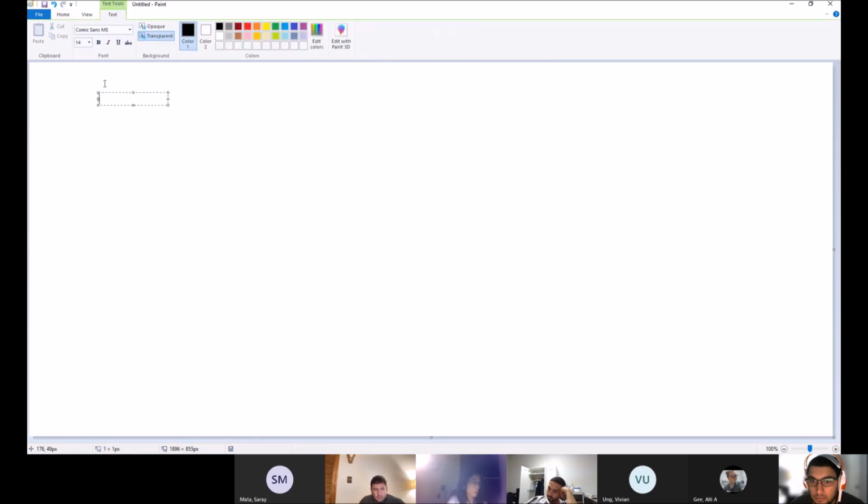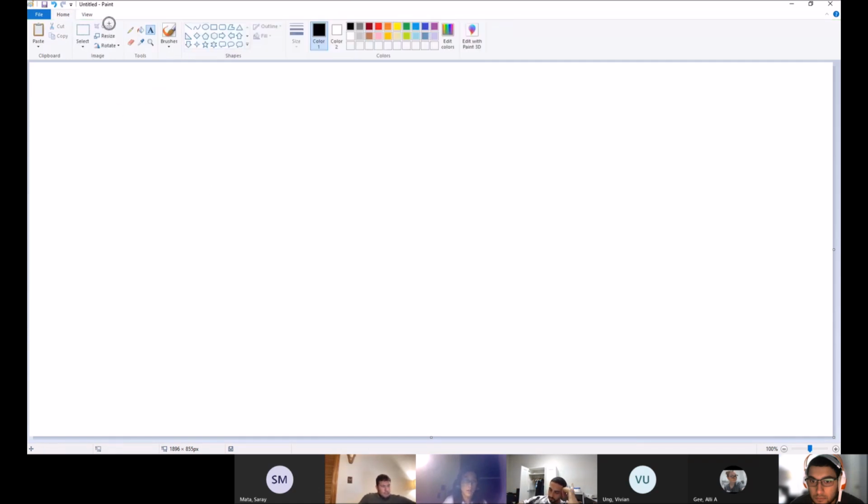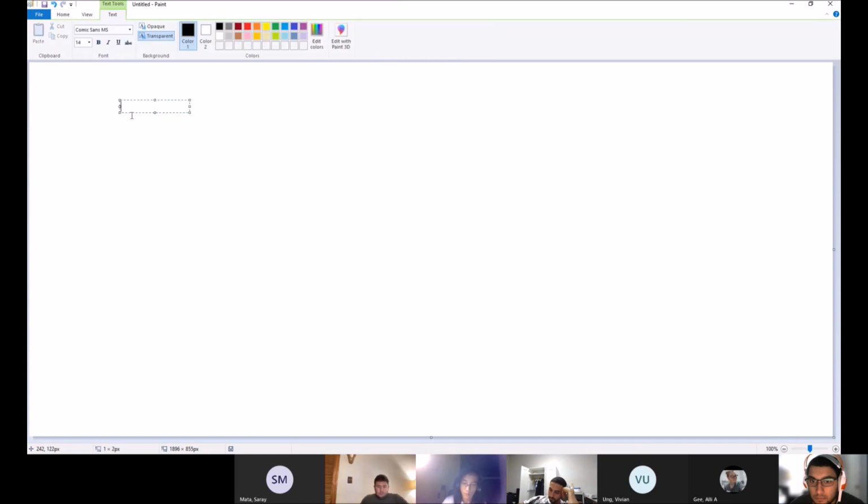So this one actually doesn't come with a picture. It tells us, given a tower that is 300 feet tall, subjected to a lateral wind load of 500 pounds per linear foot, PLF, that's what it stands for, what is the internal bending moment at the base?